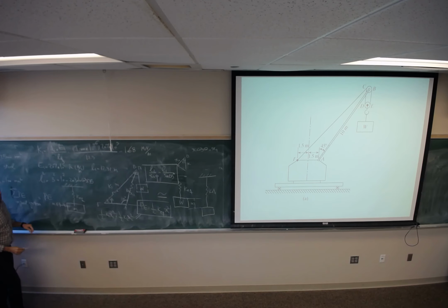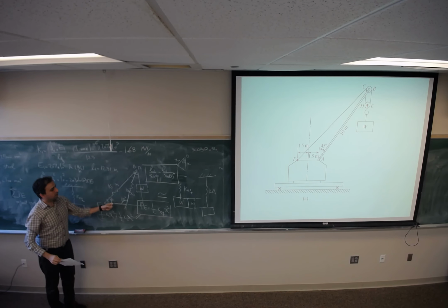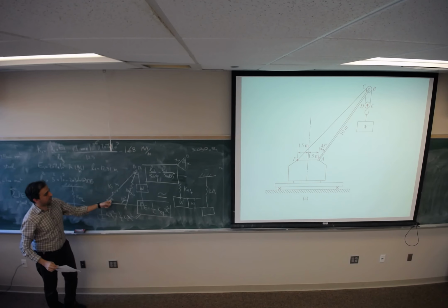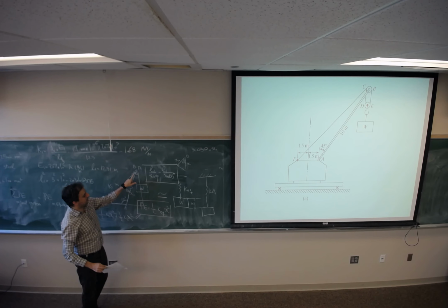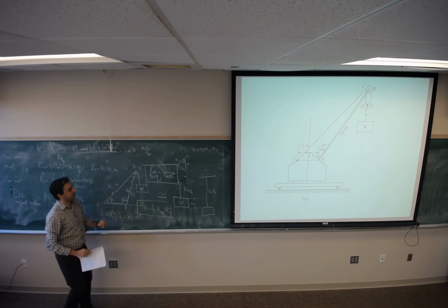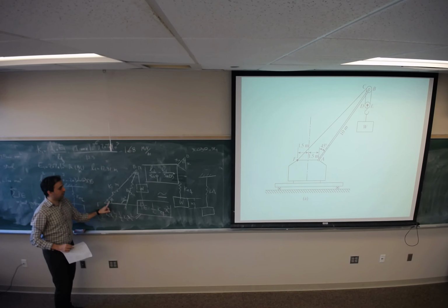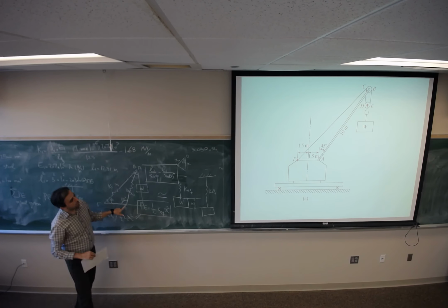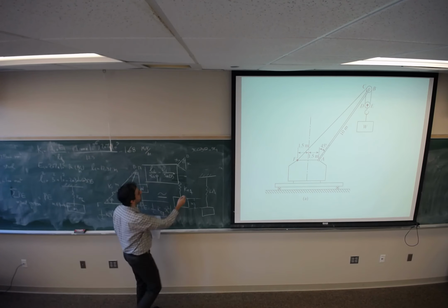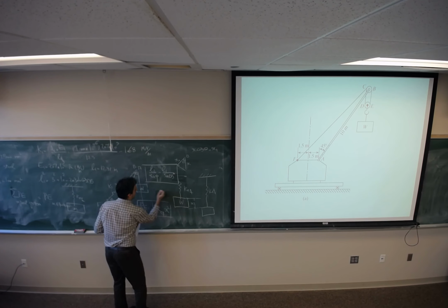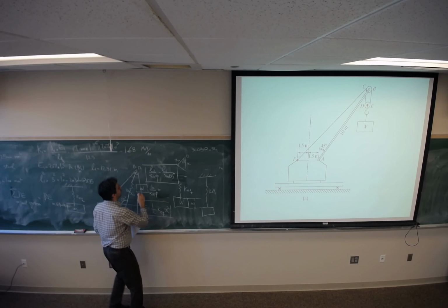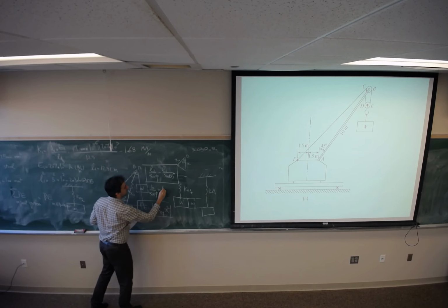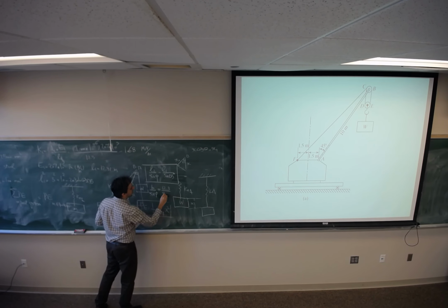I'm looking for this angle. Why do I need this angle? Because I can find angle of theta. 90 minus phi is going to be theta. So for that reason, I'm looking for angle of phi. L2 is 10 meter. 10 meter divided by sine of phi equals L1, which is 12.3 divided by sine of 135.